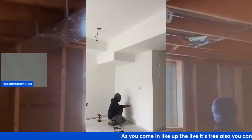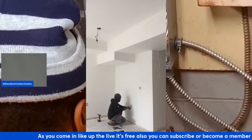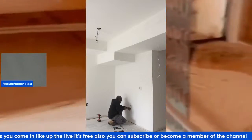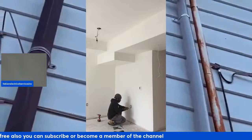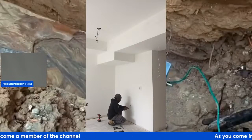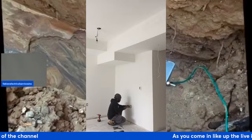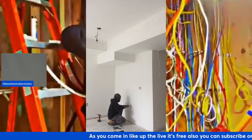Again, they are required in areas with water such as kitchens, bathrooms, and outdoors. A GFCI monitors the current flowing to a device and the current returning from it. Under normal conditions, the amount of current going out should be equal to the amount coming back in.